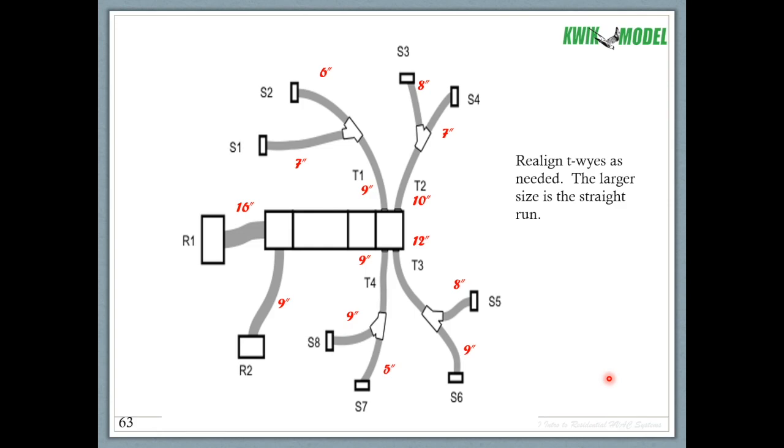So how does this system look to you? It's a 2.5 ton system moving 1,000 CFM. We've got a 16-inch main return with a 9-inch secondary return going to the master suite. We've got two 9-inch trunks, a 10-inch trunk, and a 12-inch trunk. I think a lot of people will look at that and say, that seems big to me for 1,000 CFM for a 2.5 ton system.